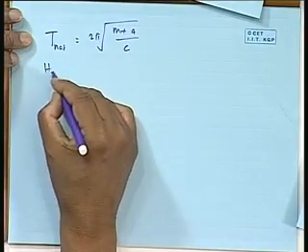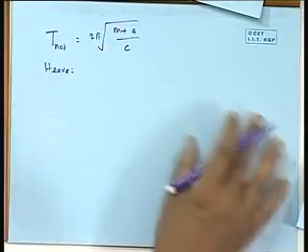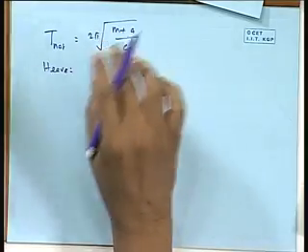Now, for heave, values for typically roll, heave and pitch. Remember that there is no C, restoring force, in unrestrained motion of sway, surge and yaw. Why? If you push a ship, nothing is bringing it back. If you shift it in the y direction, it just stays there. It's like a car, it just moved there, nothing is holding it back. Only in heave, roll and pitch, if you push it down, it gets pushed up. If you tilt it by an angle theta of 10 degree, it will come back. If you pitch it by 2 degree, it will come back because the hydrostatic fluid force will put it back.